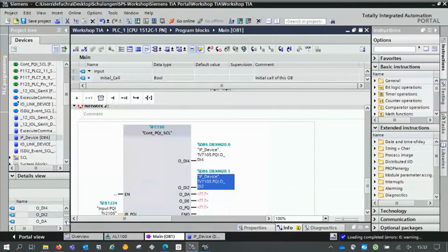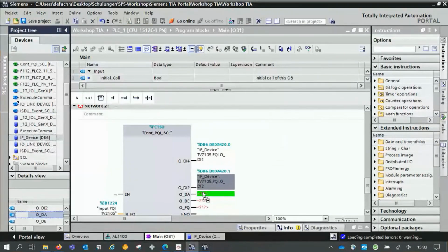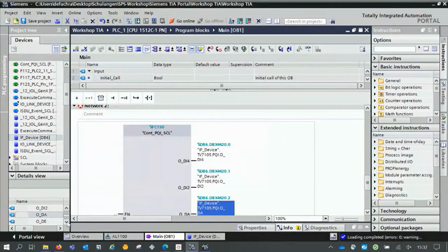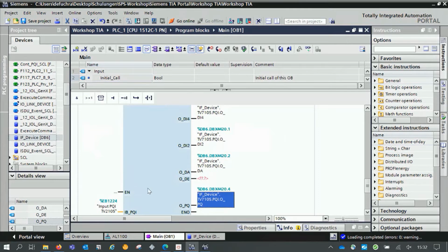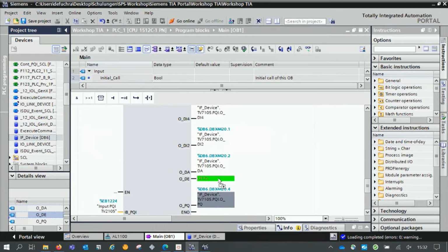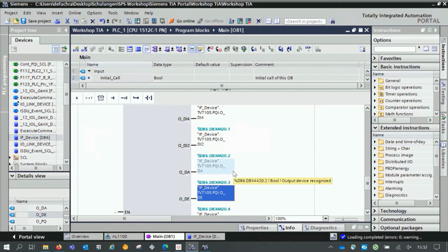And if you are using IO-Link, you get the information that communication is active, IO-Link is active. You get the information that the process value is valid. As I said, the right device and no major fault. And you get the information that the device is sending an event, a diagnostic message, to the PLC.